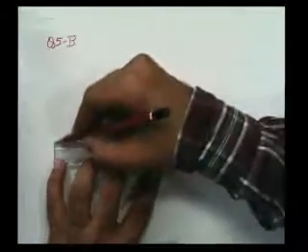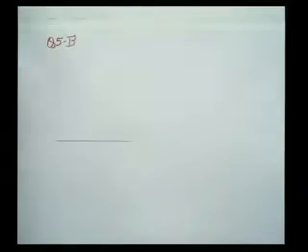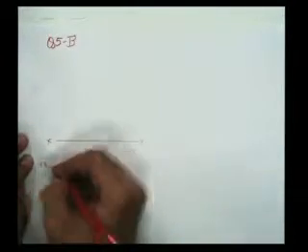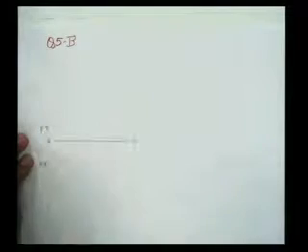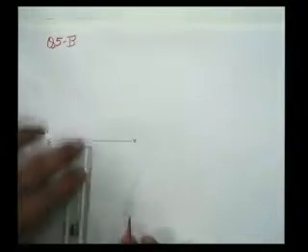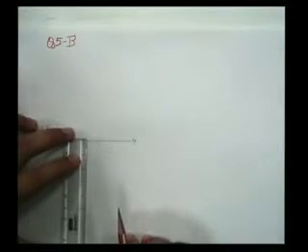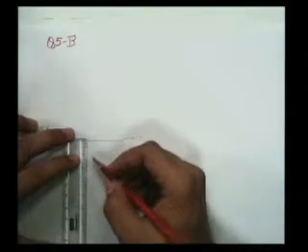Now first of all, draw a line XY. It is written in the question that a square pyramid is resting on HP such that all sides are equally inclined. So we know that below line XY we'll have the top view, and above it the front view. For getting the base of the pyramid, which is a square, what we need to do is